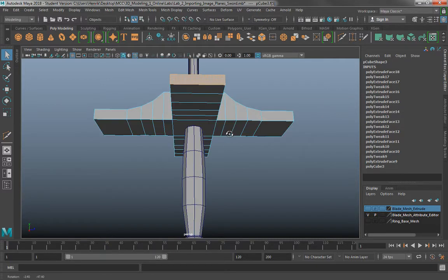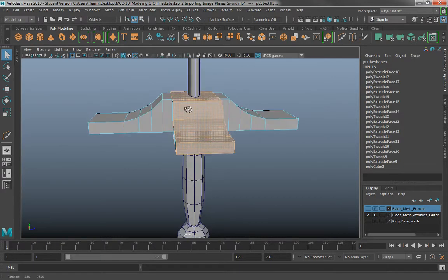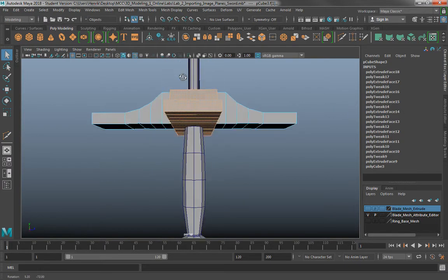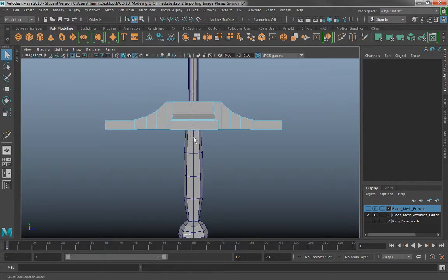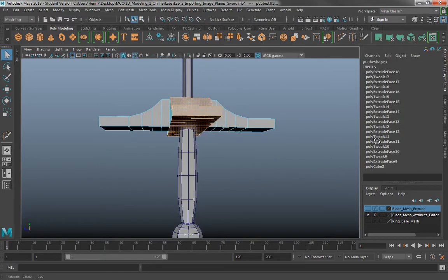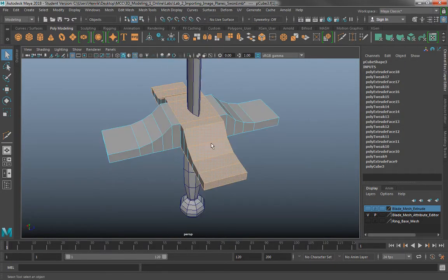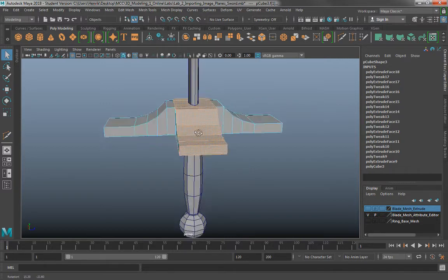One other way is I'm going to click on one face, hold Shift, and double click this very next face. It'll highlight all of these faces that I need. Another way we can select these faces, right here, click drag right down the center, and I highlight all the same faces. So what this does is it selects just like the edge. When we selected the edge loops, it's going to select the faces all in that subdivision section.